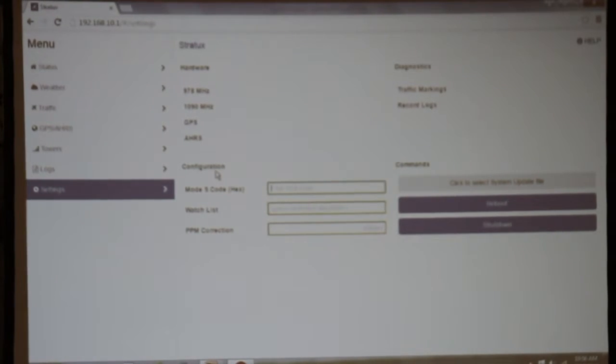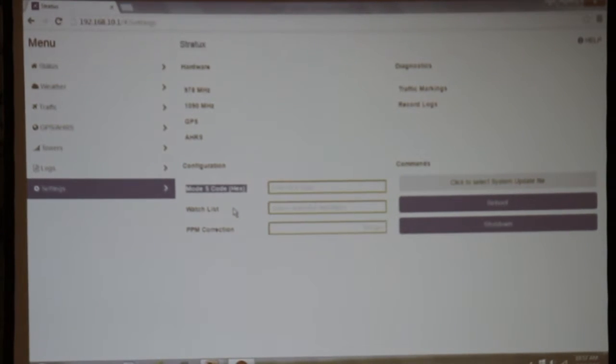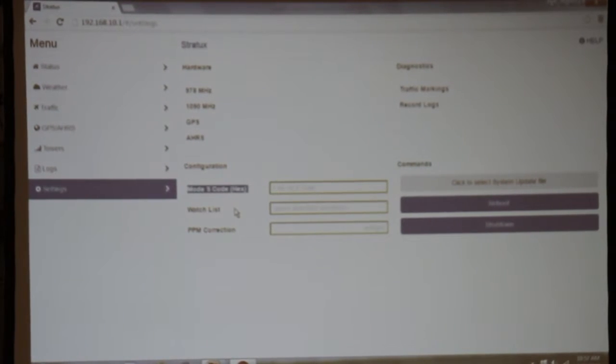So this is what is being discussed here. It's for detecting ownership, so that you get the traffic rebroadcast, but you're not showing the traffic alert for yourself. You need at least a Mode S transponder for this to actually be useful. It just sends the information to the iPad or tablet that you're using so that you can filter that traffic out. It's assigned based on the registration. You would ignore yours on the traffic, yeah.